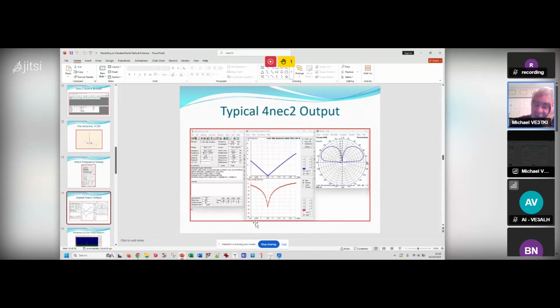If it's too low, you shorten the radial lengths, and if it's too high, you lengthen them. The only thing you have to play with is the outer half of each of the radials in this case. I was taking 3 inches off at a time off each one, and pulled it tight so the radials were 3 feet off the ground.